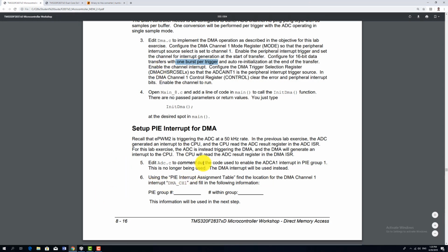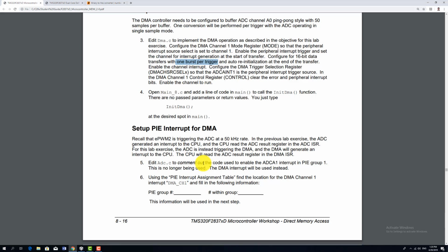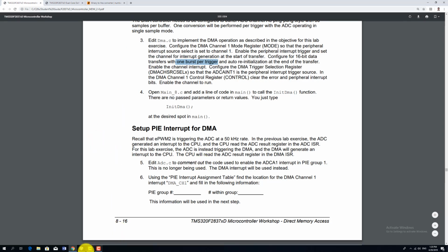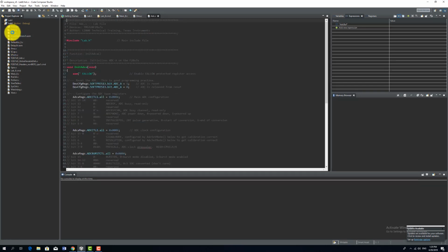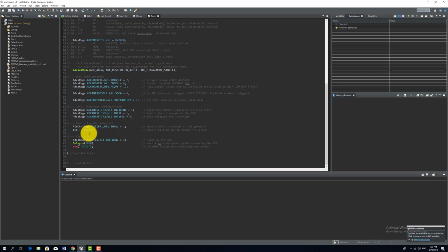to comment out. When we say comment out in C files, that usually uses comment syntax, meaning we turn part of the program into a comment so that once we run the program, it will not affect anything. Let's double check the ADC. Just click here on the ADC. We have to locate the part wherein we enable the ADC interrupt.